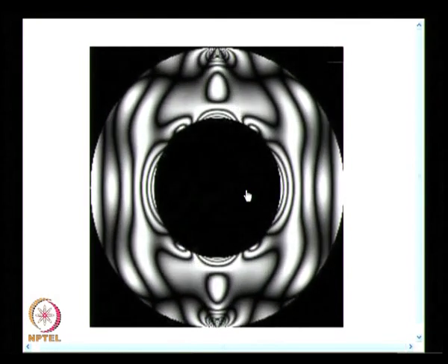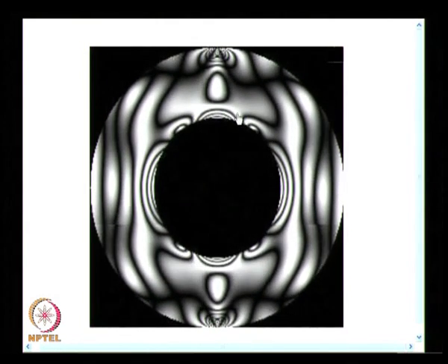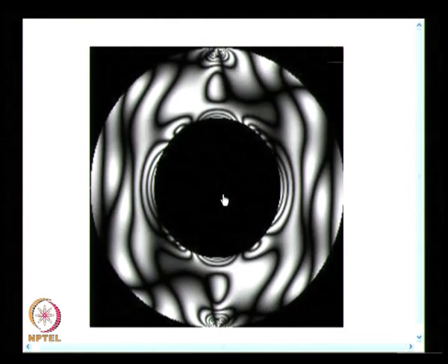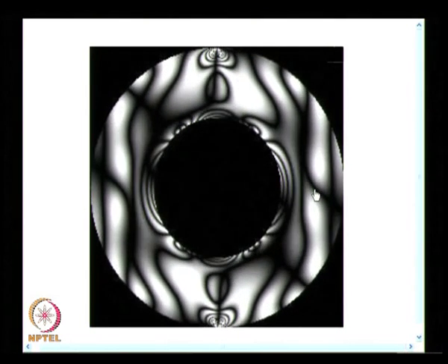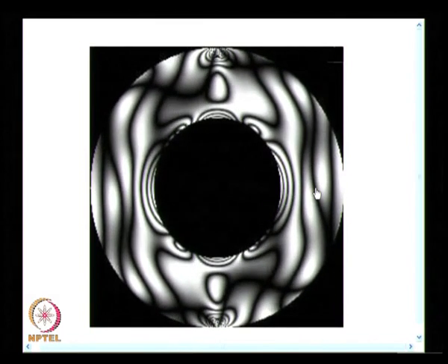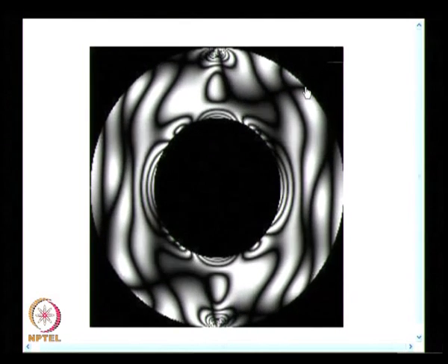The isoclinic actually rotates in an anticlockwise direction. I have all the isoclinics pass through the point. Do you not find that? Here I am continuously rotating the polarizer analyzer combination, crossed, and what you find is you always have an isoclinic passing through this point of interest, and you also find the 4 points which I said on the outer boundary. Here also all the isoclinics pass through the point of interest.